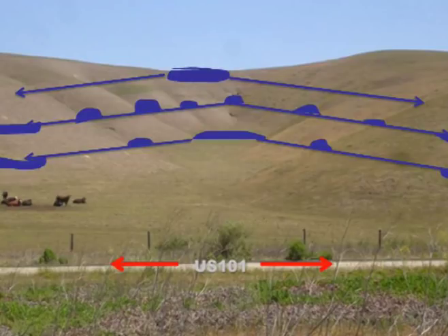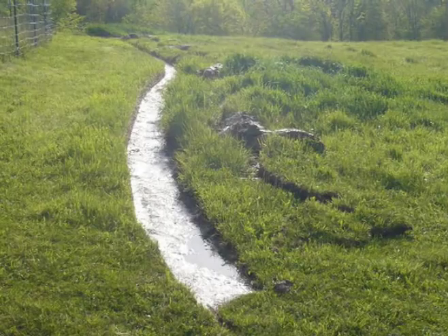So go parallel up. But there's a problem here. When we run a line, I'm a swaler, so I'm putting in swales. These are terraces, USDA terraces. They're within my 4% because they're 1% slope. As you go down slope, all of a sudden there's this little valley. All the water would come pouring out here, down that primary valley, and goes away. So instead of going like this and going ring, ring, ring, ring, which is hard to machine, I'm going to go straight across, smooth curves, whatever it is. But I'm going to have to correct there because I don't want that water to bleed away.